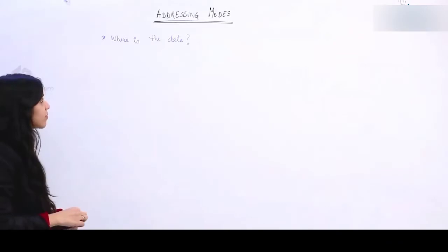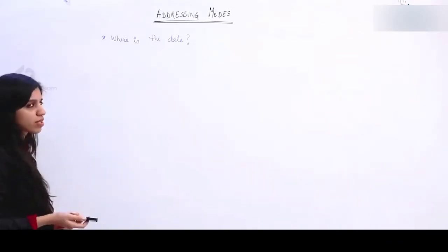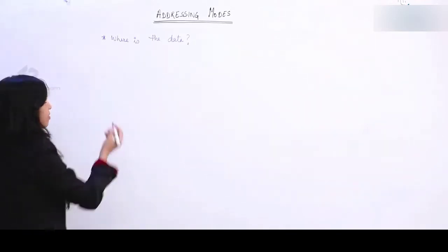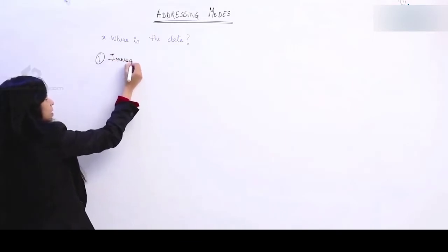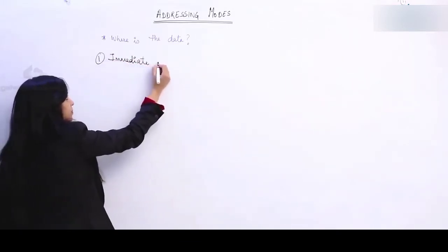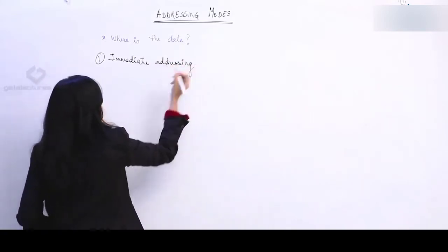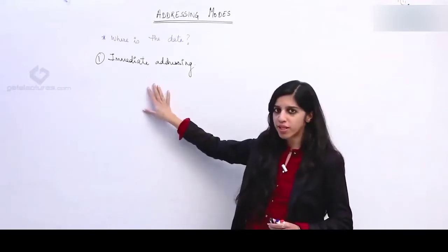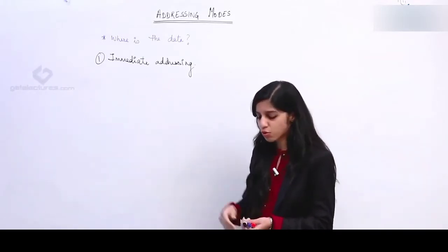We have several instructions in each addressing mode. We're going to look at all the instructions when we look at the instruction set. Right now we're just going to focus on the different addressing modes. So the first addressing mode is immediate addressing. What happens in immediate addressing is, just after the memory location of the opcode, in the next memory location, the data is going to be stored.